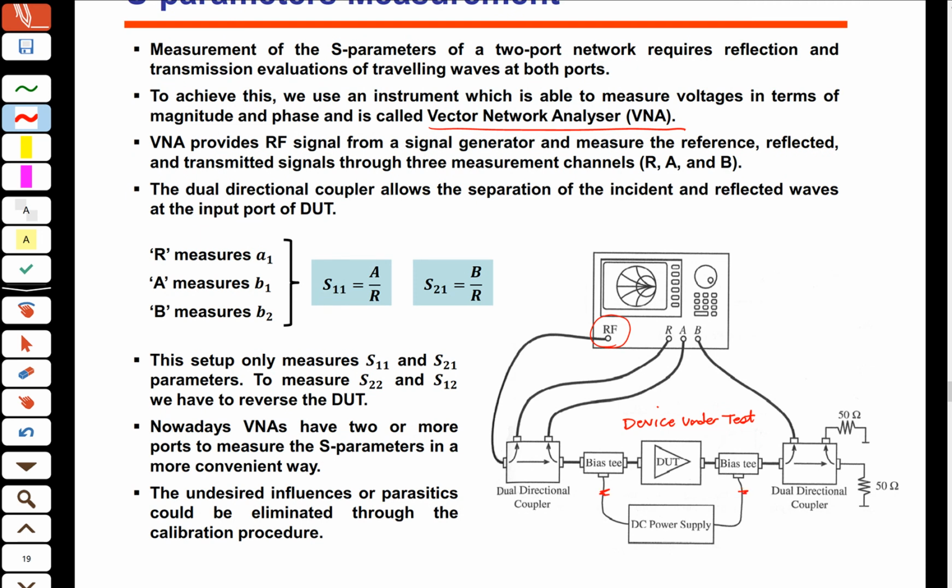So directional couplers are devices that separate the incident and the forward and backward wave. So they have two ports. When you send signal, then it directs some part of that to this port. When you send signal from this side, then it directs it to this port. So nothing, when you send signal, it does not go into this port.